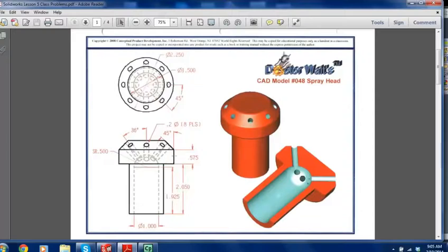I was looking at this for a few minutes and I was thinking maybe I could do an extrusion here, a cylinder extrusion, and then another cylinder extrusion, and then maybe some chamfers on here. But really this is symmetrical along the center line here, so this is something that we could revolve. It's just screaming out to be revolved. So we could revolve this entire object with just one feature, and then we could put in these holes that are on the angled plane.